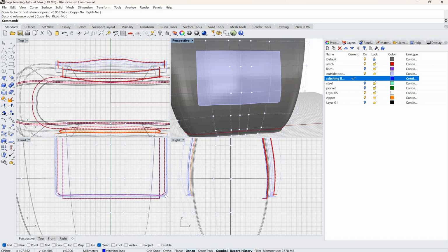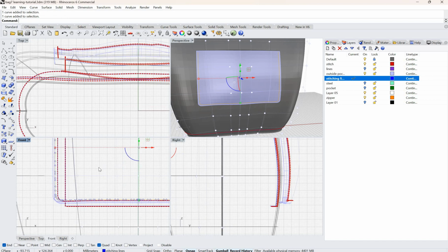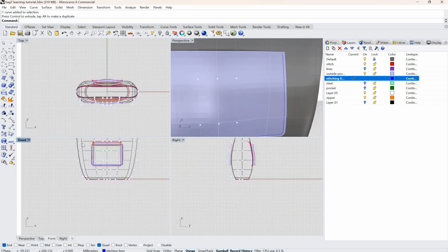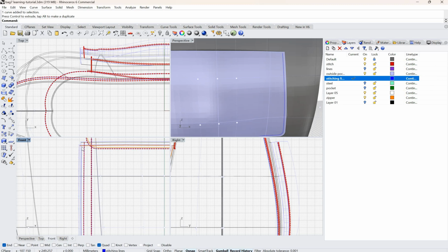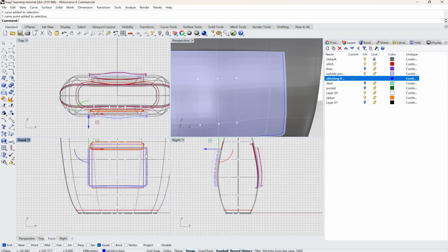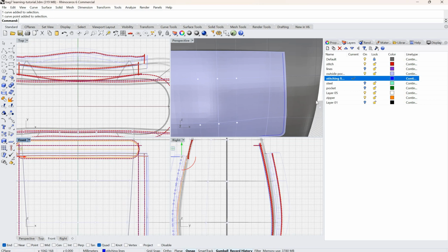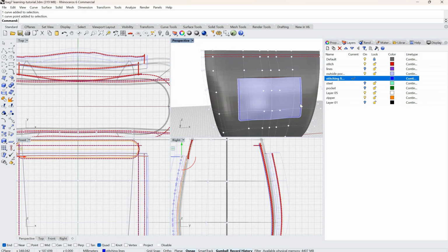And in case you're wondering that this has gone inside, so just select this one, and there are too many control points, so don't worry about that. What we can do is we can shift this out so that when we add the stitching line it shows. And I'm going to increase, probably select this control point, and first I'm going to join this, because this is separated.